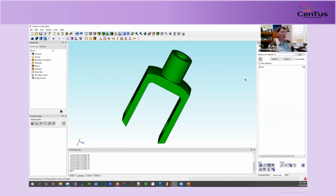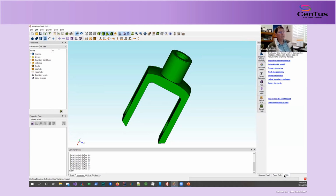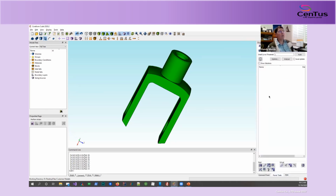So let's do this. I am in what we call the geometry, the diagnose geometry power tool. I got that by clicking on this tab at the bottom right. These are our command panels, the power tools, and item. We'll get to item in a bit. Back at power tools on the first one, I am going to do something here. Let's go to the mesh power tool, and I'm going to say, look at all the volumes in my model.